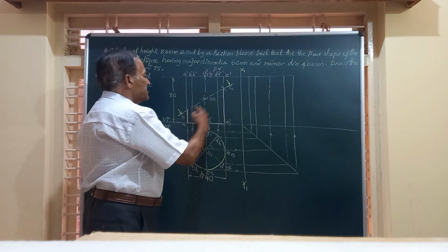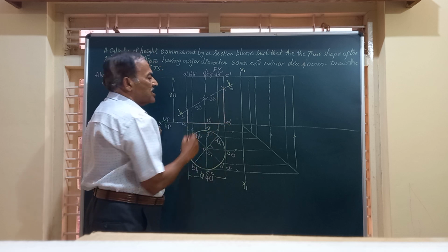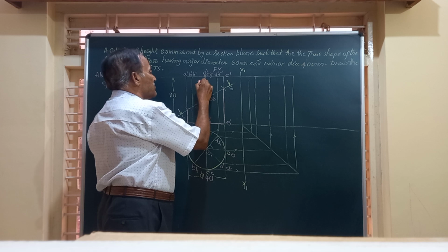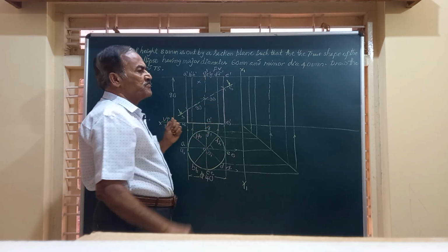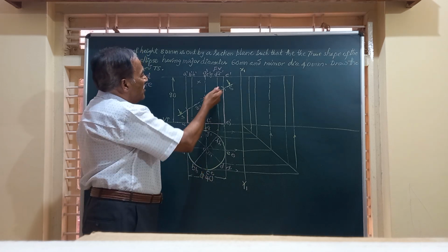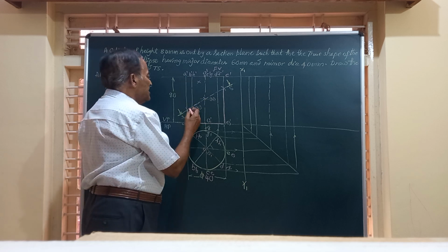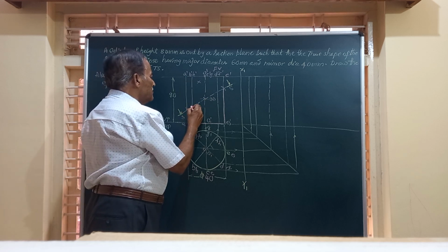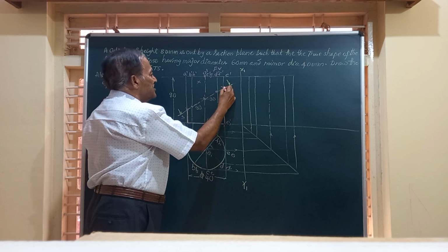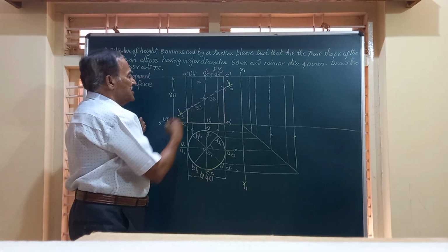Friends, now after this section plane is cutting the solid, the bottom portion which I have shown in dark lines is retained, and the portion above that is thrown out. So only for this portion we are going to have this as the front view. And friends, now after the solid is being cut, you can just observe here the generators AA, BBHH, CCGG, DDFF, and this is EE. All the 8 generators of the cylinder are cut by the section plane.